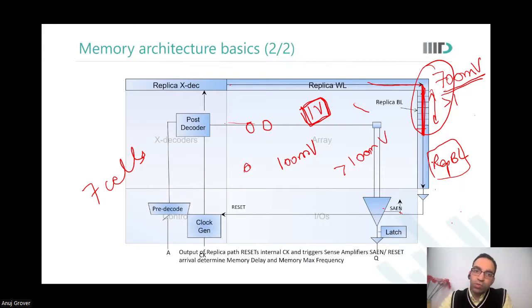Those projects which design the replica bit line or replica path, we talked about it in yesterday's office hours also. You have to take care of that. The cells are programmable. The word line is programmable, and whether it goes to VDD or ground, that should also be programmable.